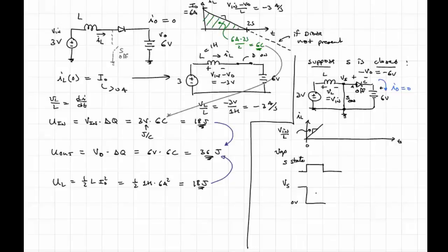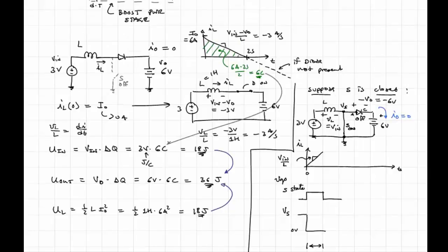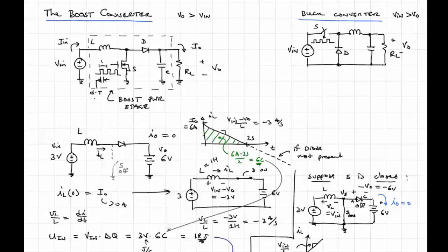And how long does it rise for? It's going to rise for a duration of however wide our pulse width is. So I mentioned that our converter puts out a duty cycle or a pulsing signal. I'll draw it larger here. We've got a period T, and we have an on time of duty cycle times T, where duty cycle is going to range from 0 to 100%.